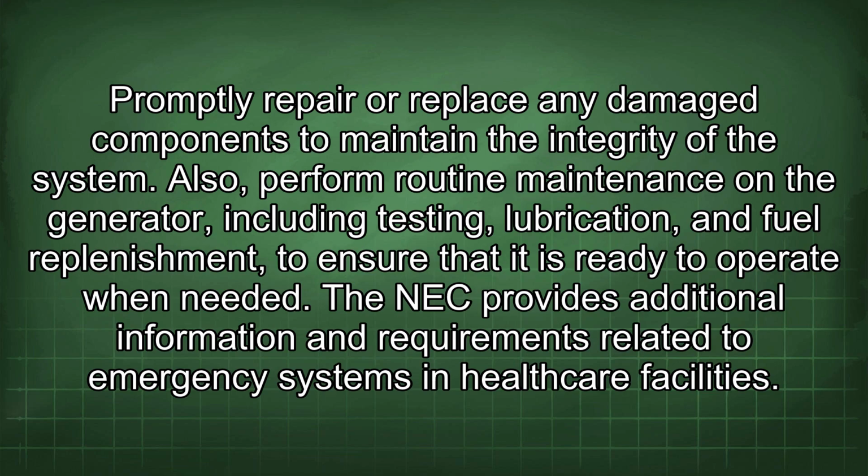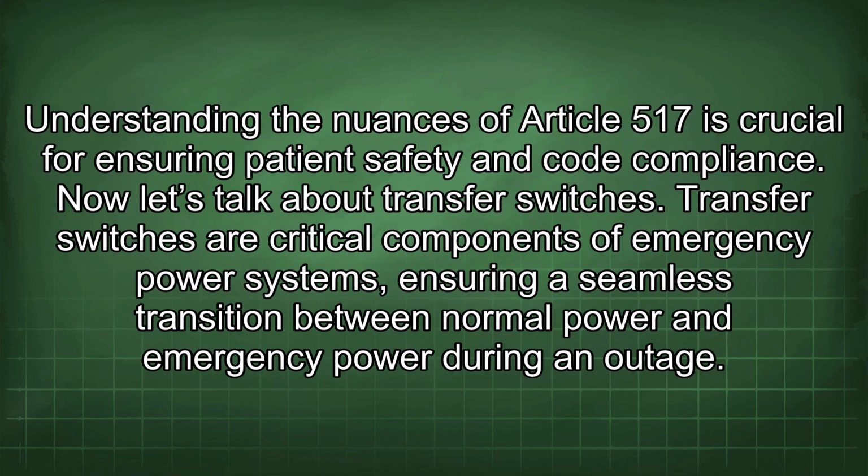Also, perform routine maintenance on the generator, including testing, lubrication, and fuel replenishment to ensure that it is ready to operate when needed. The NEC provides additional information and requirements related to emergency systems and healthcare facilities. Understanding the nuances of Article 517 is crucial for ensuring patient safety and code compliance.